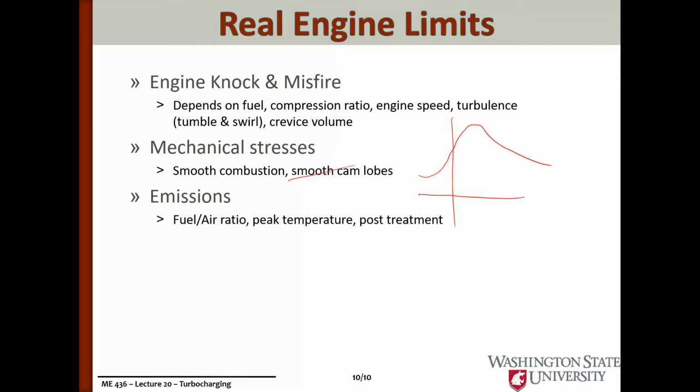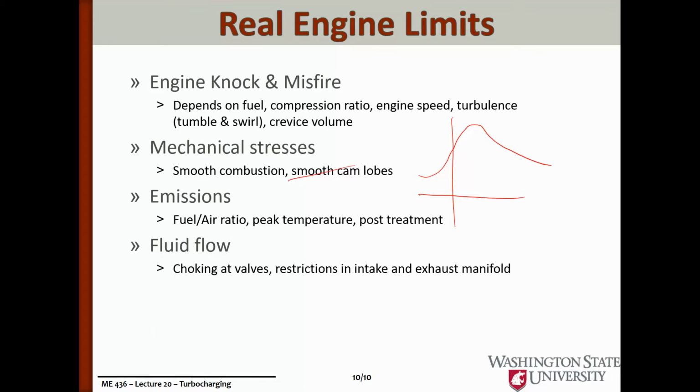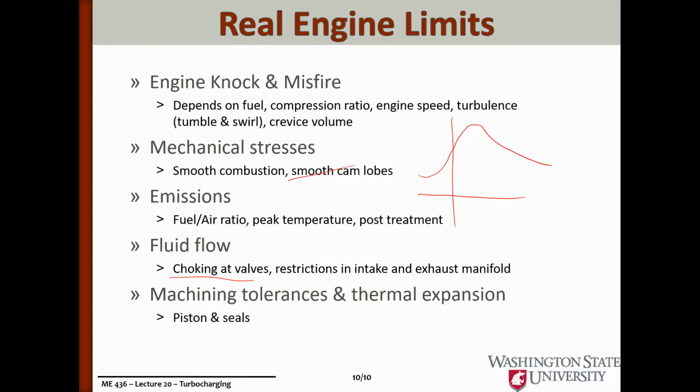We did spend a few weeks talking about emissions. What are the types of emissions, what leads to emissions, and how we clean up emissions, and those are real critical design factors in the engine. We've spent the last couple of weeks talking about fluid flow. We spent a lecture on compressible fluids and talked about the choking at the valves and restrictions on the intake and exhaust manifolds. So that's a real part of engine design today, is getting those valves designed correctly to maximize volumetric efficiency and reduce all the losses associated with that.